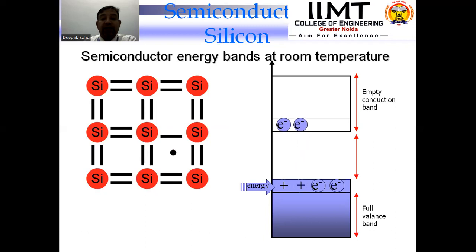So you can clearly see in both diagrams that the square space between silicon atoms represents the conduction band, and you can see how electrons move in the right and left diagram. Students, see that as the electron moves, bonds break. Here we have taken an intrinsic material in which all atoms are silicon. So bonds keep breaking in the left diagram, and the right diagram shows electrons moving. So in an intrinsic material, by providing an external energy source, this is how electrons are released.